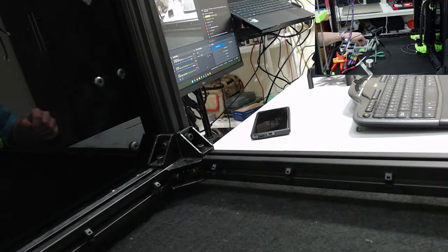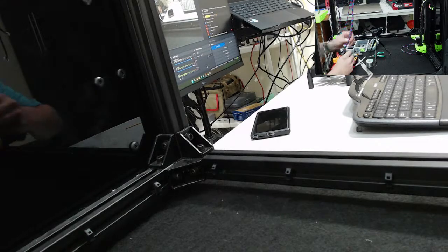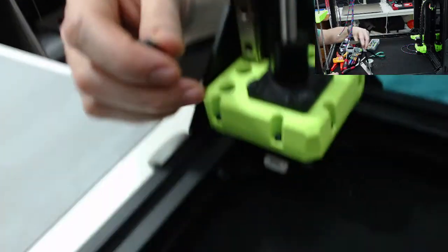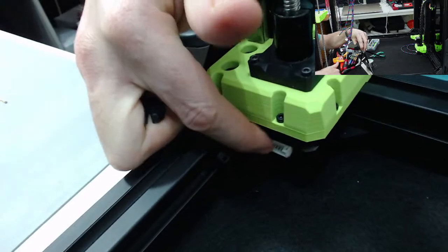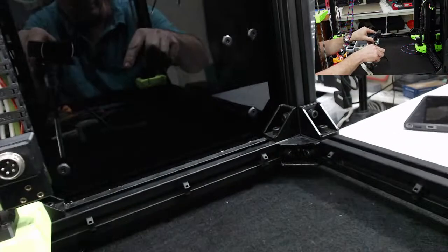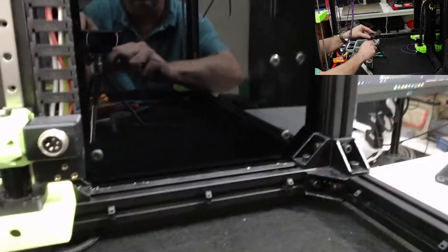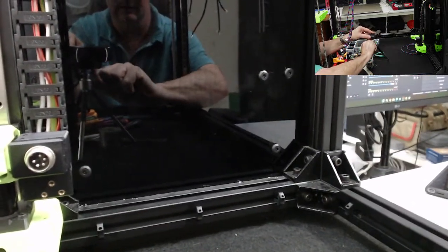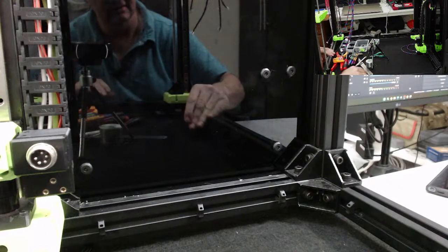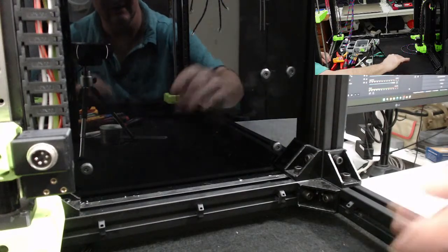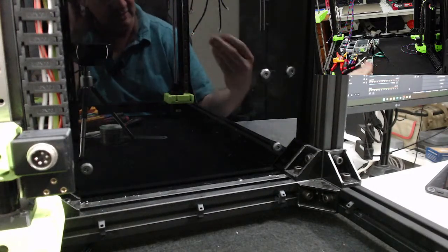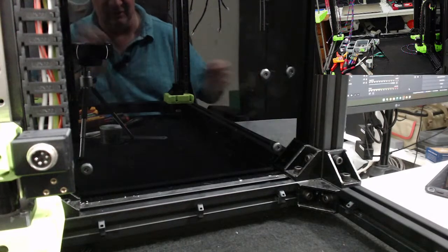So inside the bottom of the motors, we need to connect our motors all the way through to the back of the printer. We go through. Now I'm not going to drill holes anymore. I'm going to keep my wires at the bottom. I want to keep them underneath. I don't want them to come into the bed because I'm going to actively heat this chamber, so I don't want the wires inside.